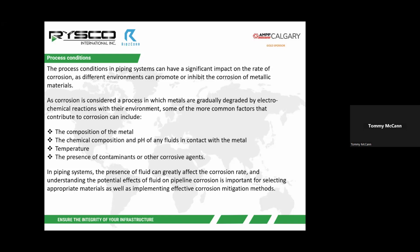So I will continue. We can focus on some of the more common factors that might contribute to corrosion. Those will include the makeup of the metal which is used, the composition of any fluids that may contact the metal, including pH. Temperature is obviously a very big factor. And then, do you have additional corrosive agents or contaminants within the system that may promote corrosion?